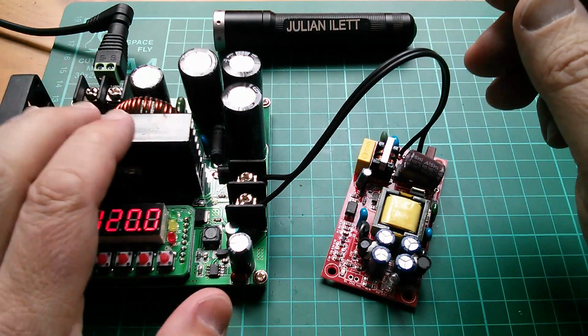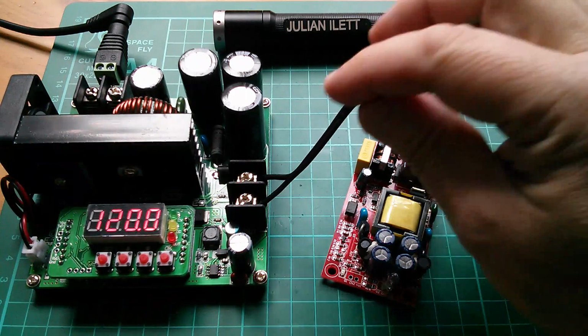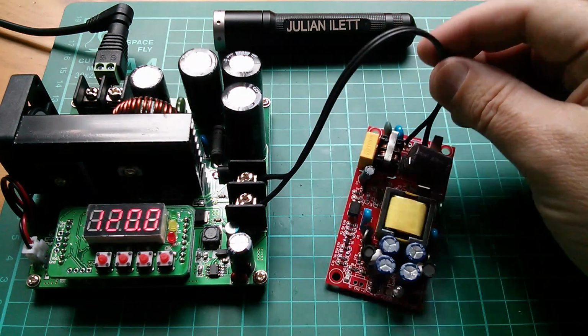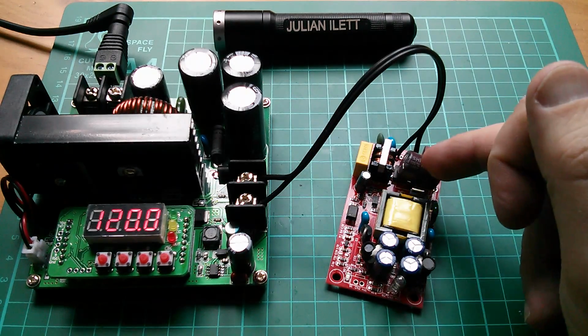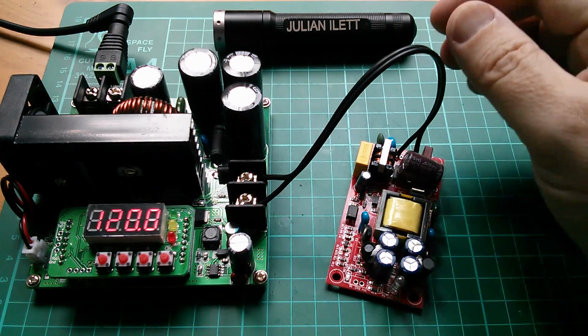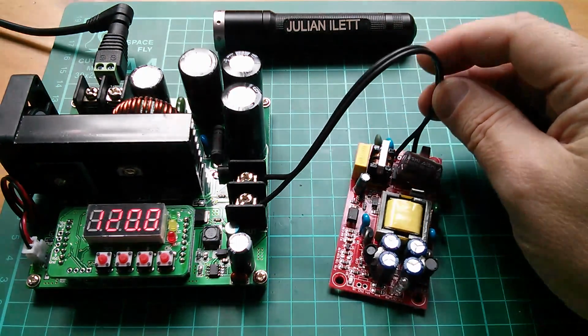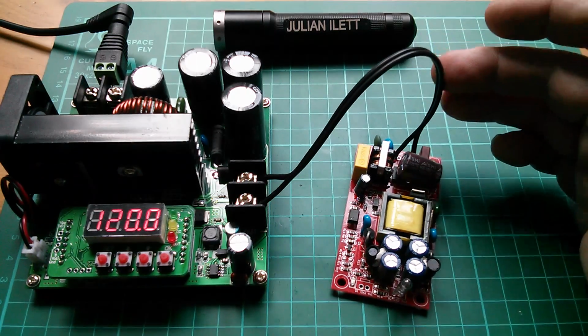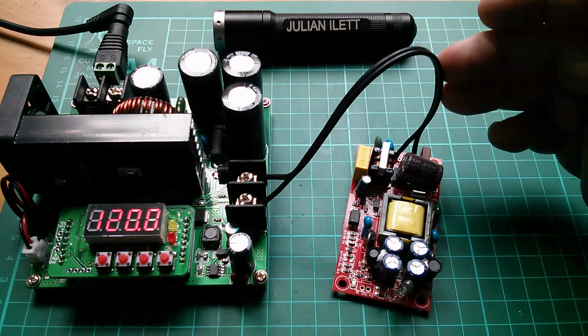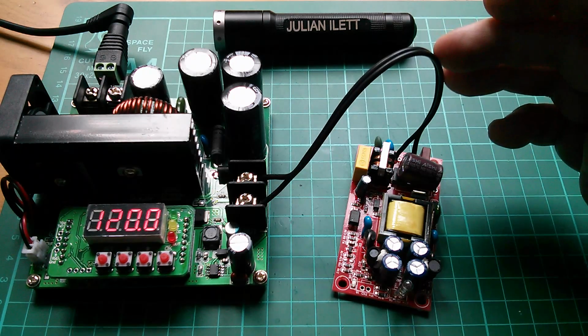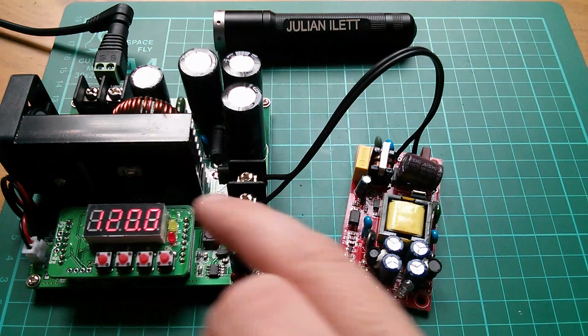So this boost converter would be outside, boost the voltage up, run it down this long length of thin wire, and then buck it, I suppose you could call it, or transform it back down to low voltage DC once I get into the workshop. Now, the savings you get by having a high voltage on a thin piece of wire are probably going to be offset to some extent by the various conversion processes.